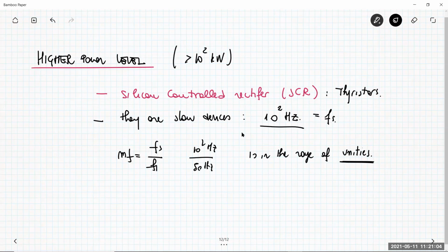They are typically very complicated to filter out, because the high order harmonics at the output voltage spectrum are very close to the frequency F1, because there is no clear separation in frequency between F1 and Fs. So filtering this kind of application could be very complicated, or basically you are using these for applications in which you are not so interested in the quality of your output sine wave.